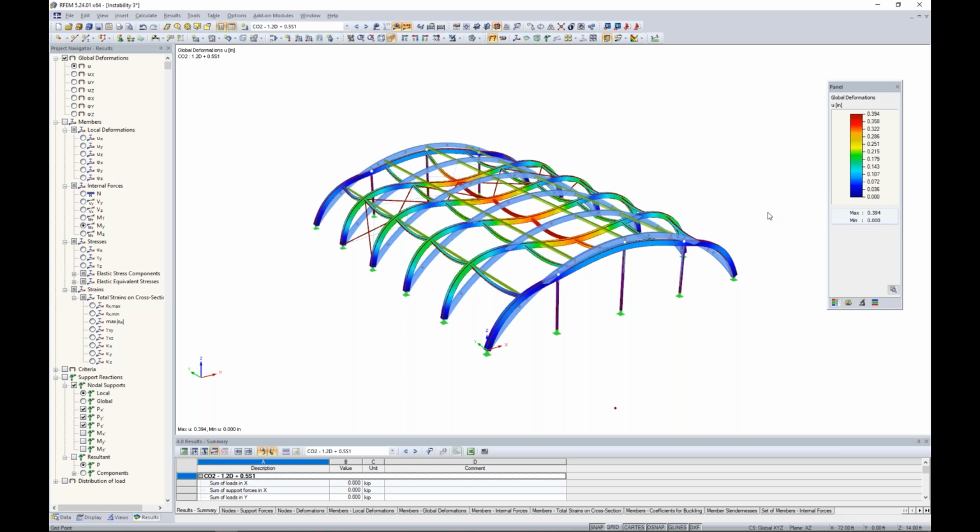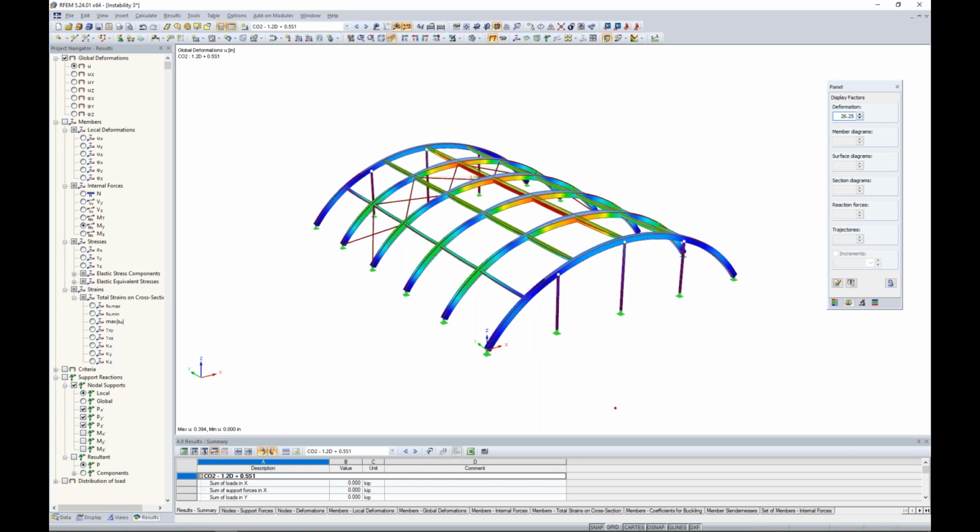And the other thing to check is, do we have any crazy deflections? If you see things just flying off the page, well, you know that there's probably, again, some type of modeling error when the deflection according to a first order analysis is pretty large. But in our case, if I decrease this deformation factor and I look at our total, 0.4 inches. So really nothing too wild going on here. So why can we not solve according to a second order analysis?